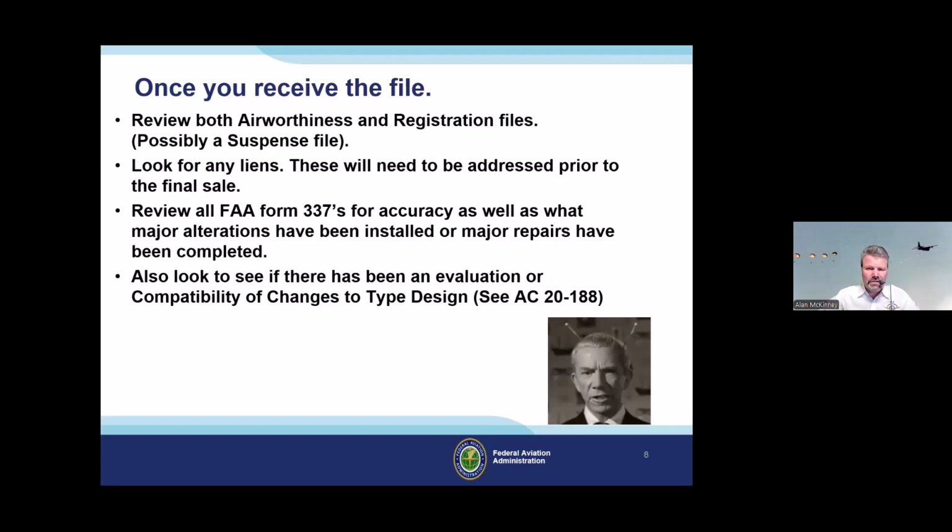Not only does Block 7 cover the individual for returning it to service, there are approved and rejected blocks. Make sure that whichever one is applicable is checked, because if not, then the paperwork wasn't done correctly. And it should be addressed before you purchase the aircraft.